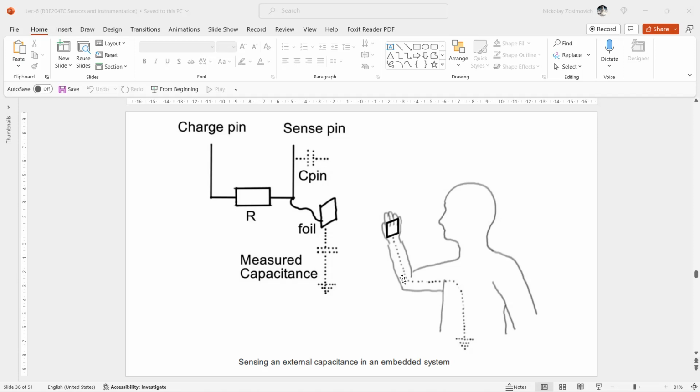After this, the capacitive sensor can be fully discharged by making the detection pin an output, simply short-circuiting the capacitor to completely discharge it. As soon as the capacitive sensor is completely discharged, the cycle can be started again. But we should note here that no analog voltage is measured, just the time it takes to fully charge the capacitor formed by the foil and human presence.